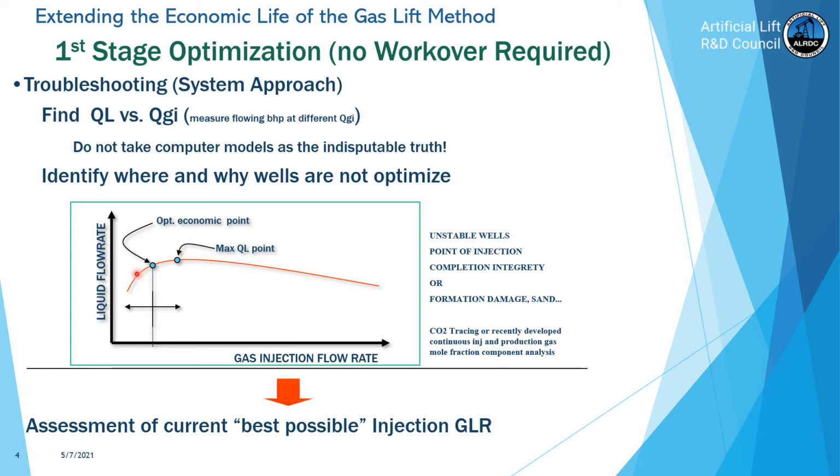Keeping in mind that we should never go below the minimum injection gas flow rate where we run into instability problems, and also if we go too far and we inject too much, we also get instability problems because we might be opening and closing an unloading valve.